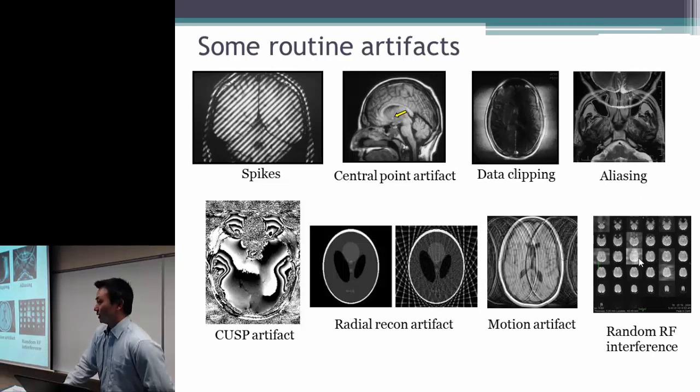Whenever the door of another MRI scanner room is opened, its RF is leaking into the corridor and into our scanner room. That may be the cause, but we are not quite sure. As long as the door of the other MRI scanner room is shut, we hardly see this kind of artifact.